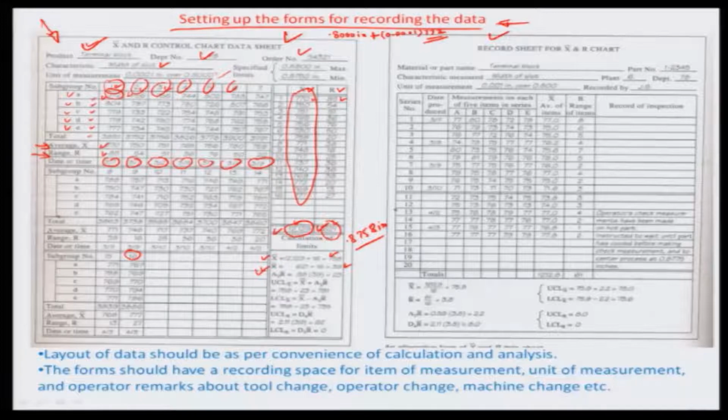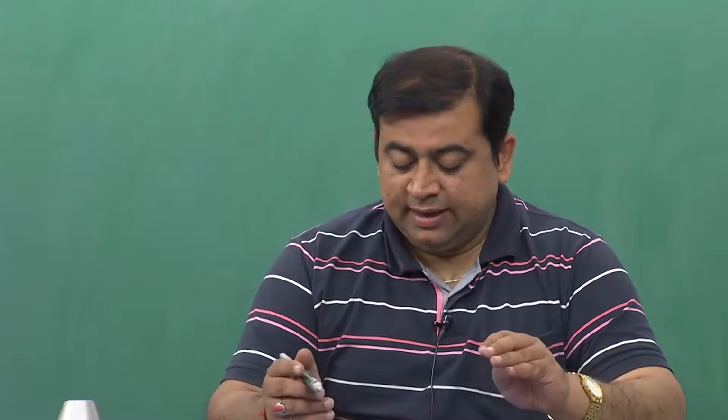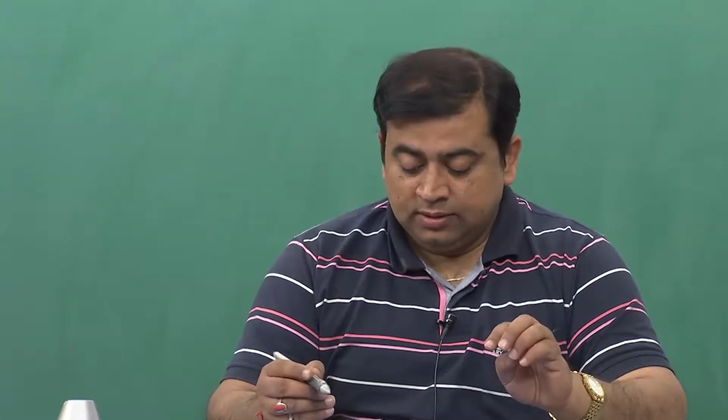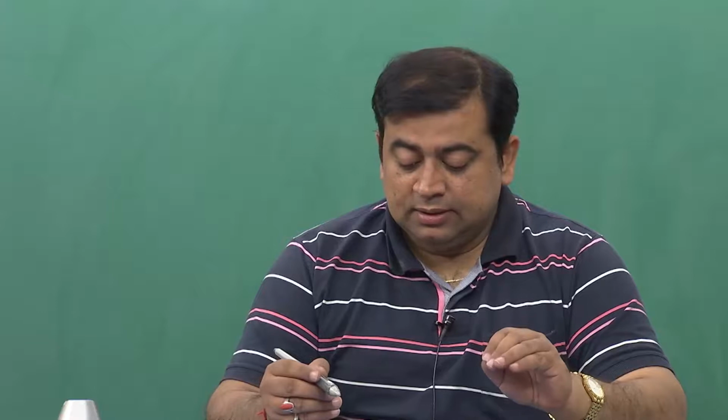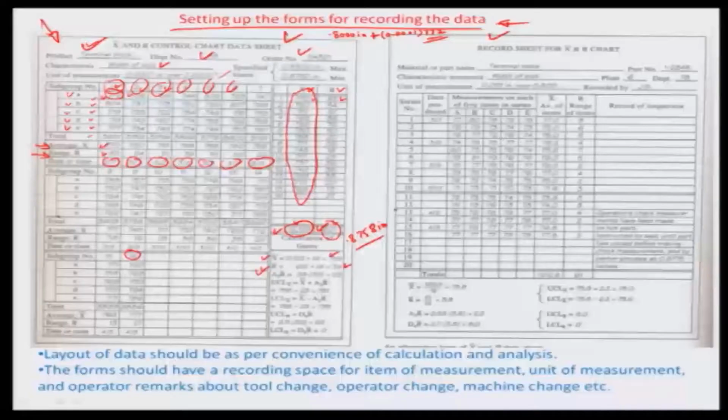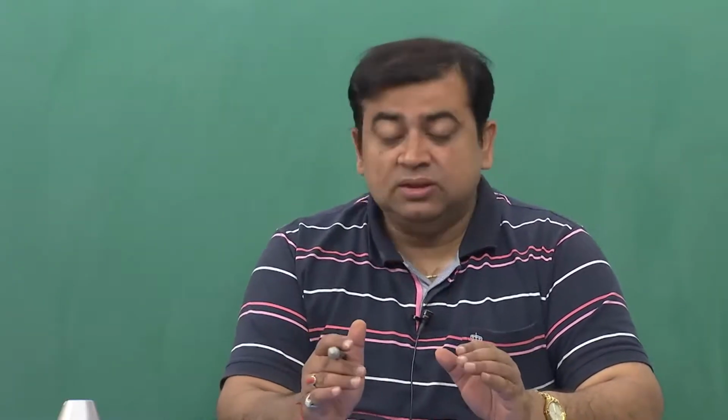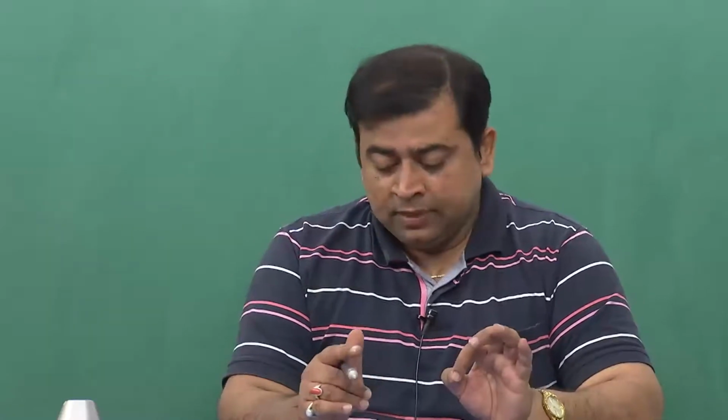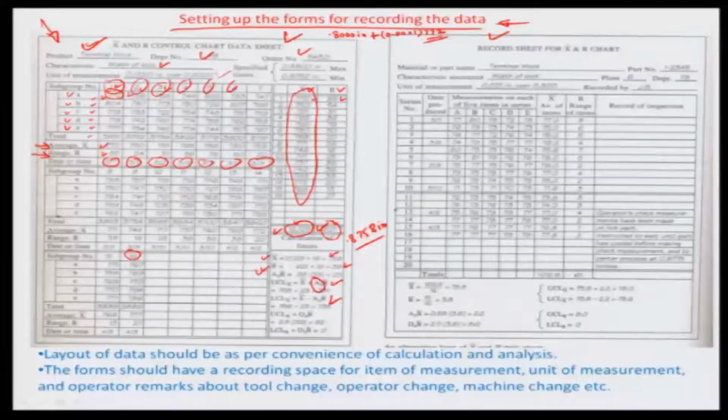Having said that, now you have to go back to the Shewhart control method, where they talk about the factors which are associated to plot the X chart. Typically there are 2 control limits that have to be set. One is the upper control limit of X, another is the lower control limit of X, and I am going to share that table with you a little later along the process. But as of now, just think of it in this manner, that based on the subgroup size that you have obtained, you can select the A2 value and the A3 value.